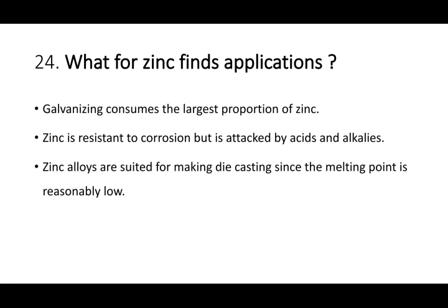Next question, what does zinc find application for? Galvanizing is the best application of zinc. Galvanizing consumes the larger proportion of zinc. It is nothing but a surface treatment. Zinc is resistant to corrosion, but it is attacked by acids and alkalis. Zinc alloys are suited for making die casting since the melting point is reasonably low.